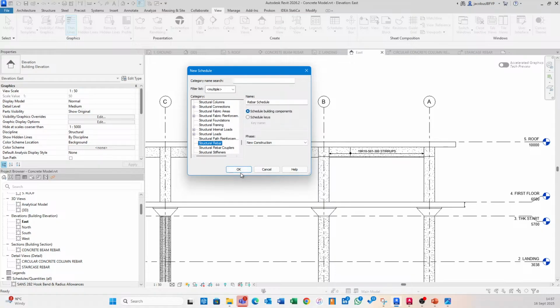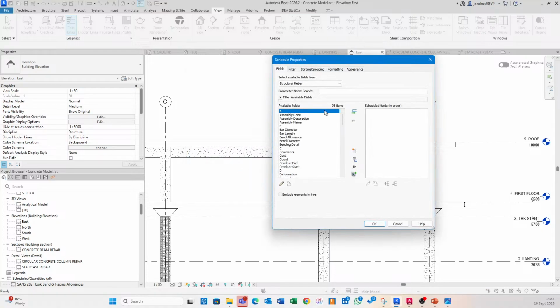There we go. Okay, so now we have the A, B, the total length, etc. But there's a bit of a problem in that, firstly, Revit, with how these properties are assigned to families, does not necessarily assign the same A, B, C, D, or E value to a particular leg of the rebar shape. So that's one thing to consider, and that might require that you go and modify that